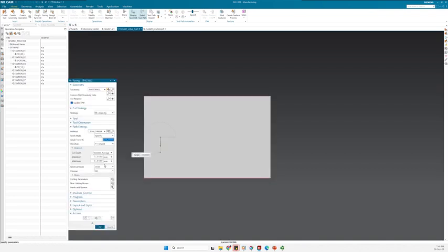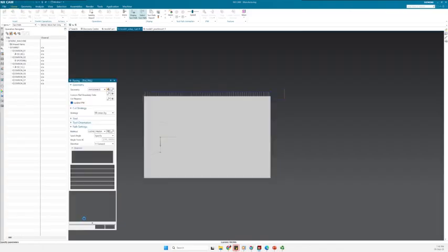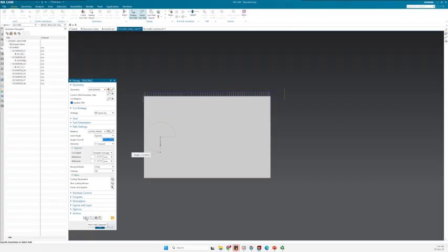Click OK. Then after that, I have the menu. Before we do anything, let's do the auto generate, to just see, without making any changes, whether the geometry is showing the material removal that I'm looking for, or there is an error that I need to figure out how to solve. If I now generate the toolpath, I can see that it's already in a wrong direction. I just wanted to do the facing.